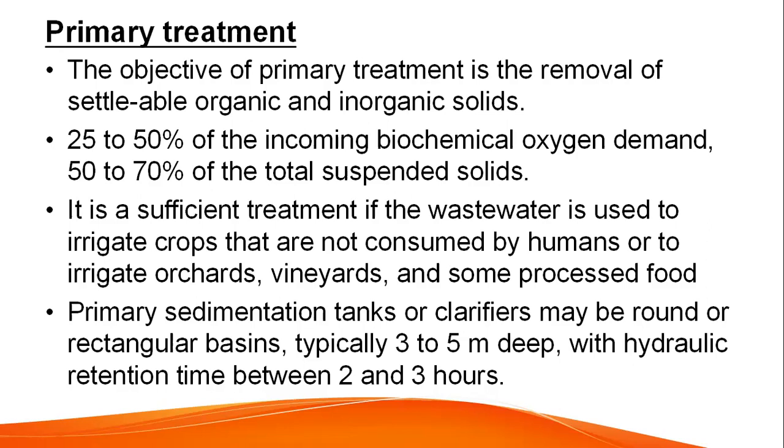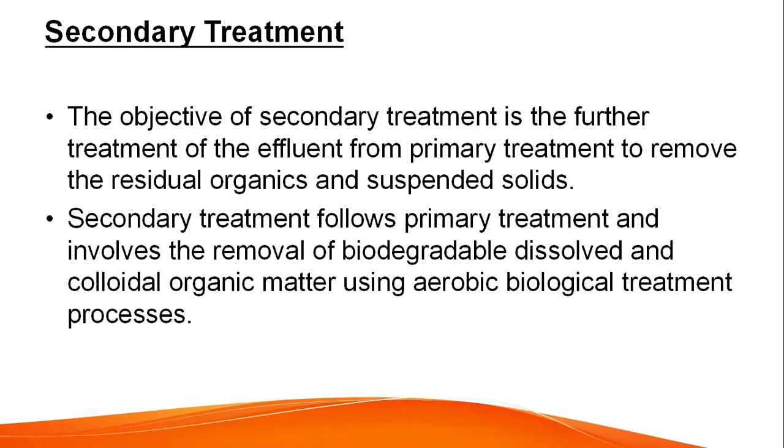Primary sedimentation tanks or clarifiers may be round or rectangular basins, typically 3 to 5 meters deep, with hydraulic retention time between 2 or 3 hours. This was the primary treatment. So moving towards the next slide, seeing what it says.